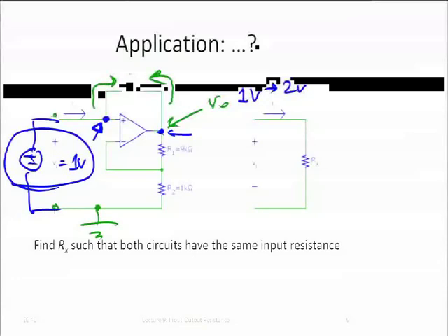And if you have a short circuit, if you actually make RF equal to 0, then you get into a mathematically, or at least practically, totally idiotic situation. You have this source telling what the voltage is there, and then you also have the operational amplifier telling what the voltage is there, and if they're not equal, how are they going to fight it out? They're both infinitely powerful. It just makes no sense whatsoever, right? So yes, you're absolutely right.